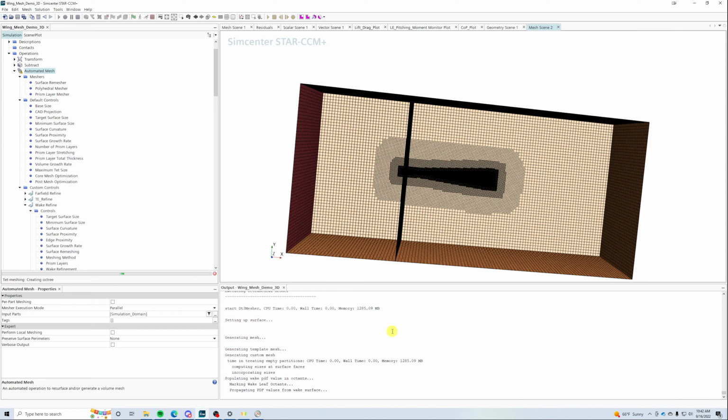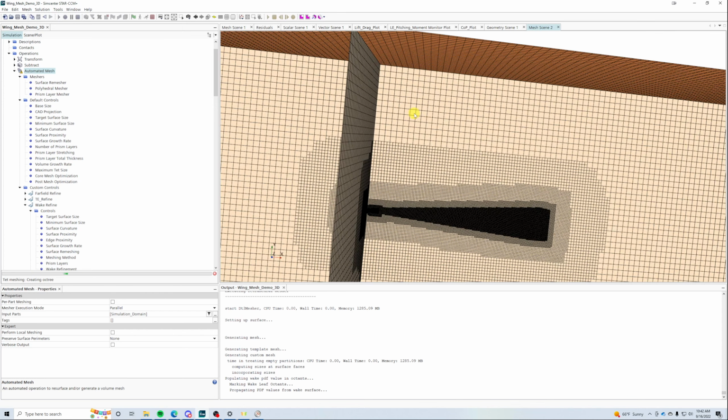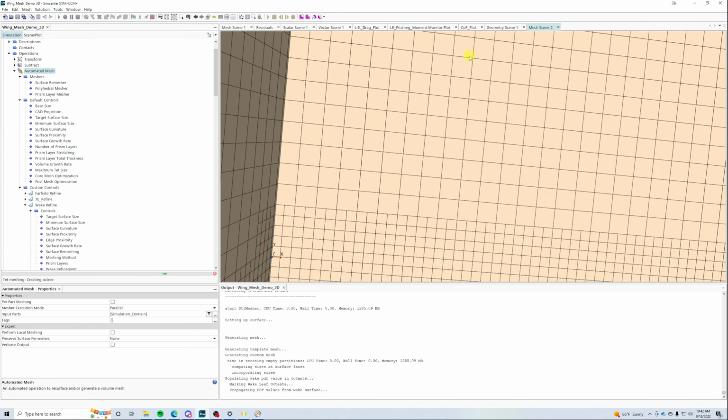It is still very serviceable for most applications, but it is slightly less good, slightly less efficient in cases where the flow direction changes in weird increments. And that can be things like supersonic flow, where you have shock waves at arbitrary angles that change the flow by like 10 degrees or 20 degrees or 30 degrees. Trim cell meshes tend to not deal very well with that because all of these cells would have the flow going that way instead of largely that way.